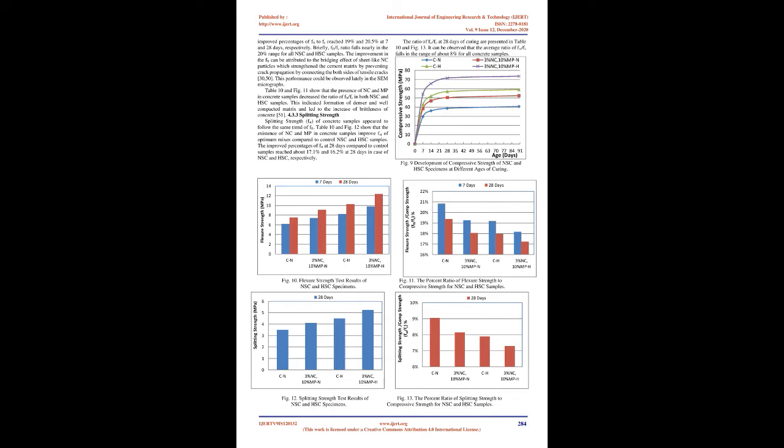30-33. The sprinkling after stirring technique was more effective compared to the individual sonicating or stirring technique. This means that NC agglomeration potential can be successfully eliminated using this technique. Moreover, this technique is practical and can shift the use of NC from the research area to industry. Concisely, at all ages, 5% NC addition using the sprinkling after stirring technique in the mixture led to obtaining the highest compressive strength compared to using other dispersion techniques.